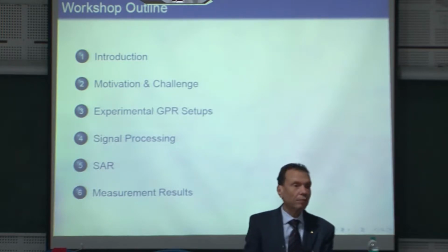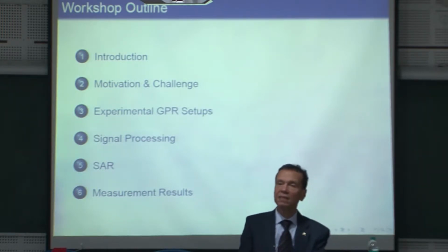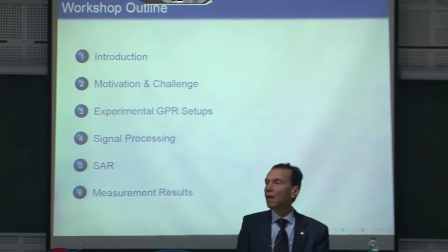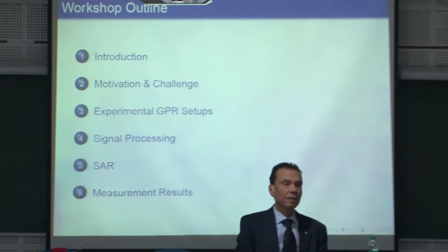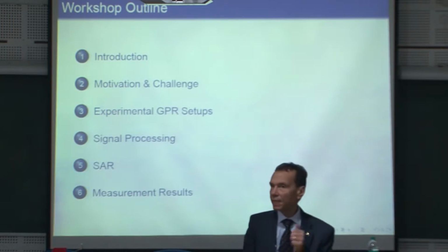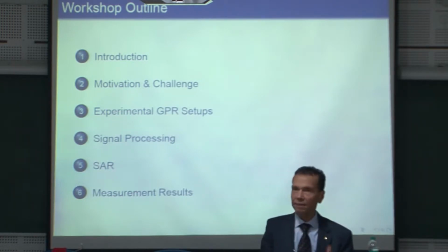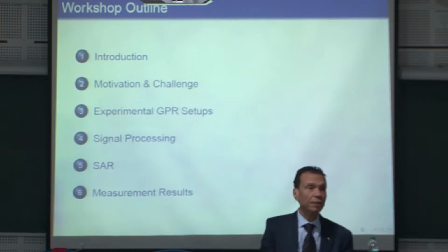And you can imagine now, you can calculate very, very easily at this frequency with this distance, how much resolution I can have. SAR is clear. So this SAR is not more and not less than a single antenna, whether receiving or transmitting, which moves in 1 dimension or in 2 dimensions in order to synthetically create an array.